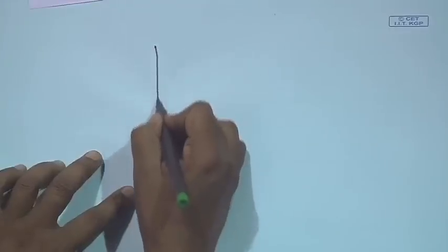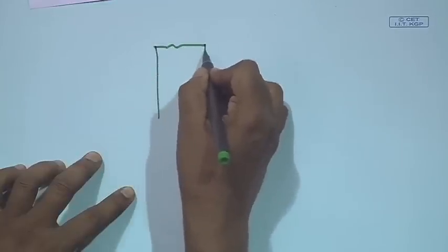The splice plates are designed through the connection through its flange, because the bending and compression are taken by the flange, and shear will be taken care of by the web. Therefore, we will design a web splice for shear. If we recall the earlier diagram, web splice for shear, we can see that it is something like this.